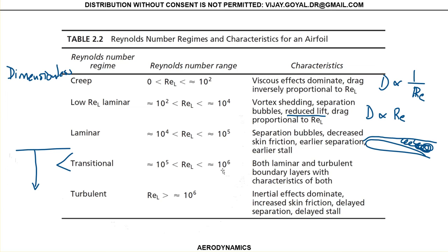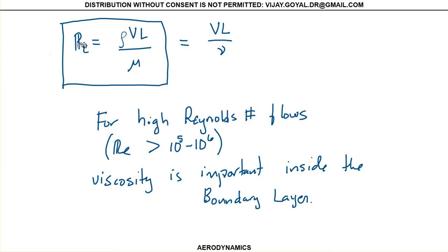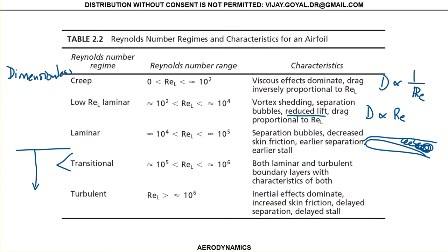I know this sounds a little bit abstract and hard to understand, but all you have to know is the Reynolds number. That's the density, the speed of the stream times the length, divided by my viscosity. That's going to give me the Reynolds number, and it is a dimensionless parameter. And I want to make sure that for my problem, you remain somewhere over here.